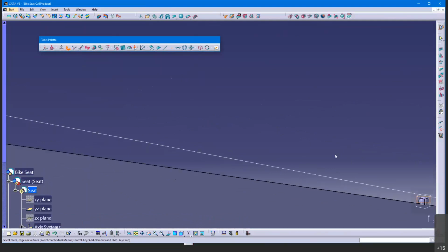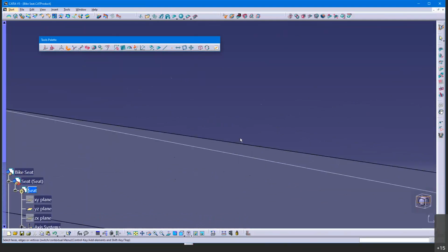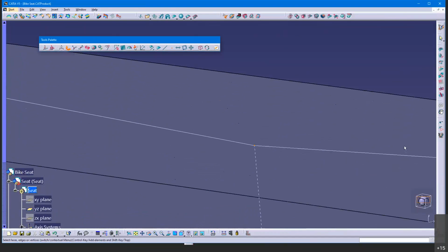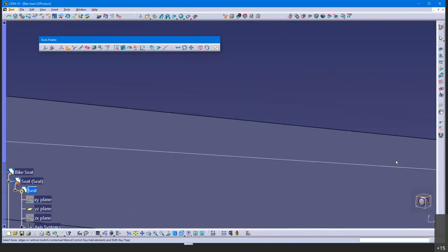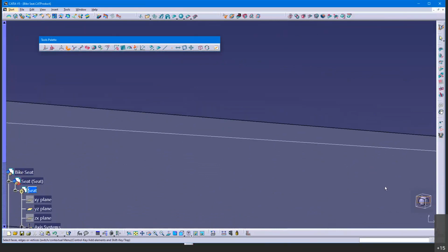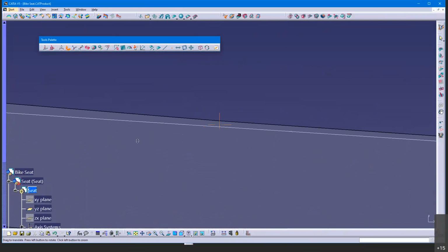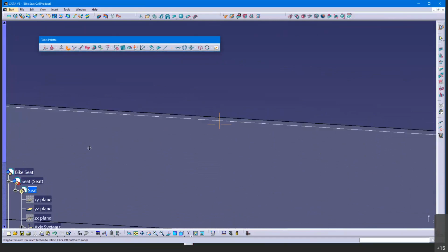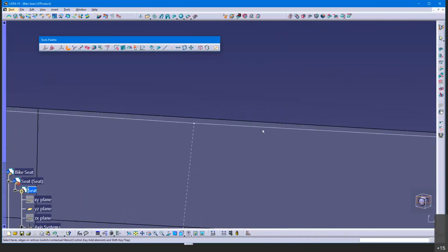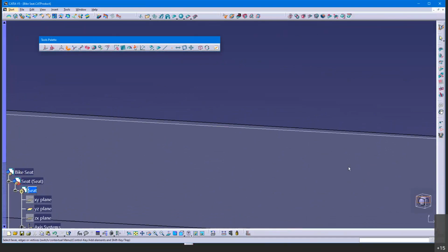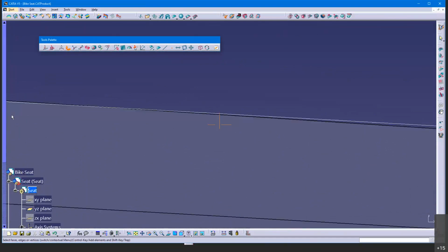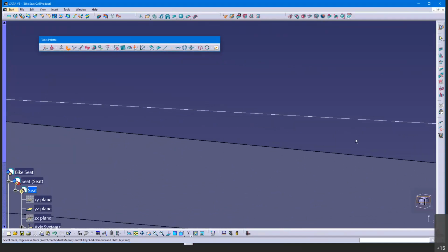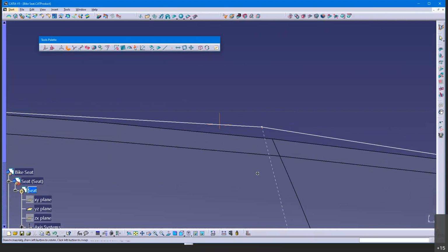So just do that final little check. There's only 6 of them, I think. Or is it 7? That's good. That normality is very important. If you don't have that normality there, you don't have a good seam. And if it's a reflection, it's a seam that's going to have a reflection over it. You can see it in the reflection if it's a high polished surface. All right, enough there.